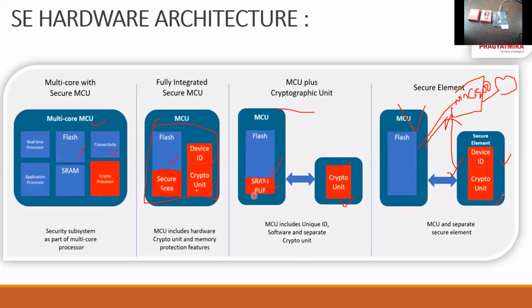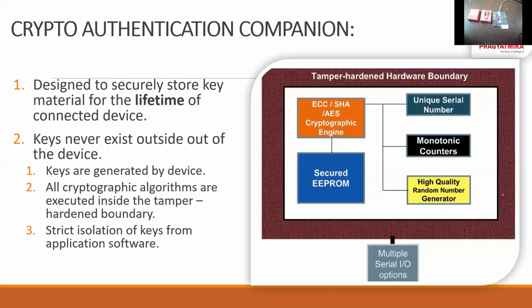There are different companies that have secure elements, but the most used secure element in the industry is the Microchip secure element, and that gets connected with any semiconductor. It is not only for the Microchip controllers, but also with the others, ST, Renesas or NXP, Samsung, all other microcontrollers can be connected with this crypto element, irrespective of the number of bits. So even 8-bit devices can also be connected. Even if you are designing ESP-based projects, like many of you are designing ESP and Arduino-based projects for hobby applications.